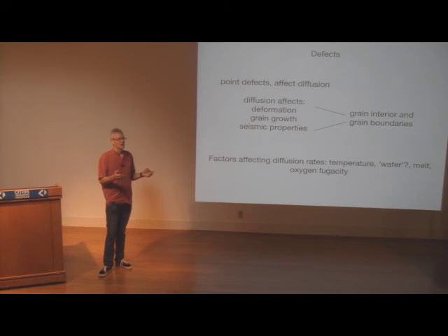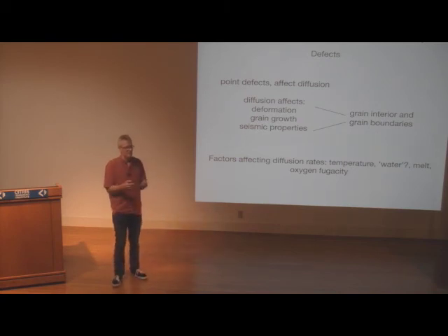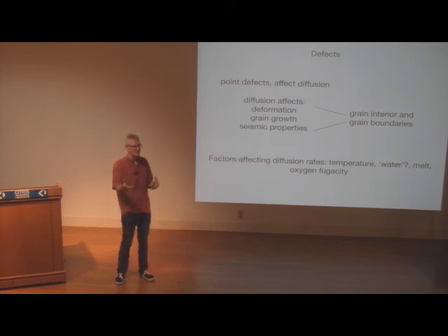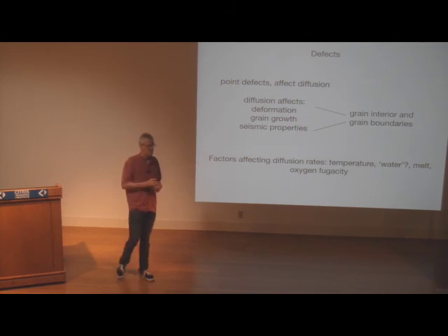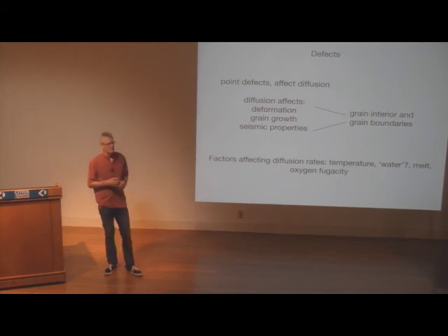But if I have a flow law with a particular set of parameters for activation energy and for A, I can't just change one without the other. It would mean, basically, if I just change the activation energy and leave A alone, I can't fit my experimental data anymore. Sure, but presumably you have some data points that narrow down the slope, which you use to get the E, for example. Yeah. Right. And so that information is still in there, even though you lose the information about the absolute creep rates. Right. Yep.